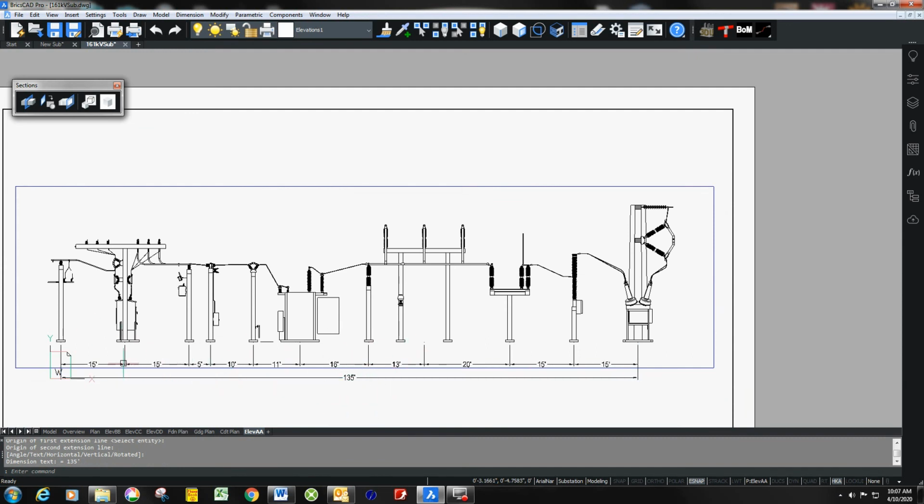You'll notice I've set my dimension style to have these not show inches where they're feet, and I get into a couple of problems. If you go back and change it where it shows 5 foot 0 inches, then you don't have room inside this one for your arrow lines and arrowhead, and it can be even worse on some of the others that we'll look at later.